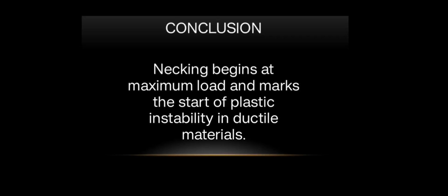Next, the conclusion on instability in necking. Necking begins at the maximum load and marks the start of plastic instability in ductile materials. It covers strain hardening behavior, and it is important for safe mechanical design.